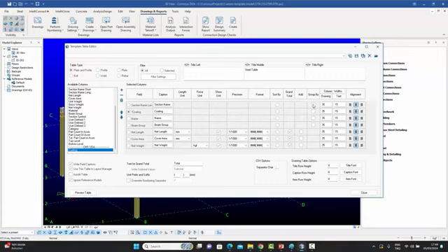Now, obviously, the purpose of these tables is to take totals, subtotals, and grand totals of fields like weight and area and length, etc. So you have these options over here of group by, add, and grand total, and these three in conjunction can be used to basically give you all the combinations that you want.